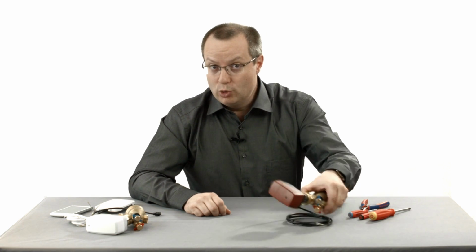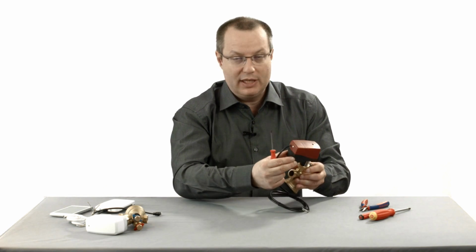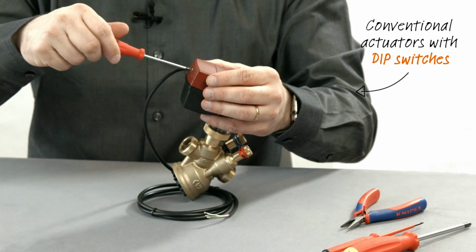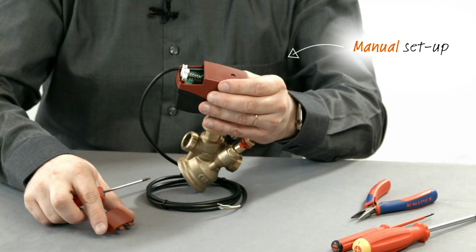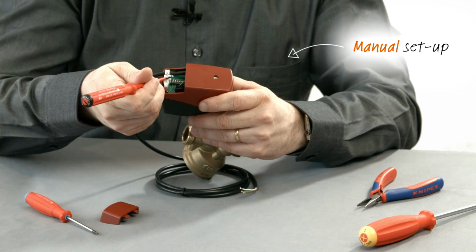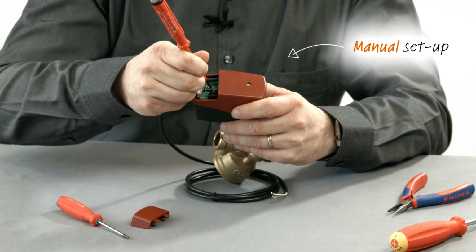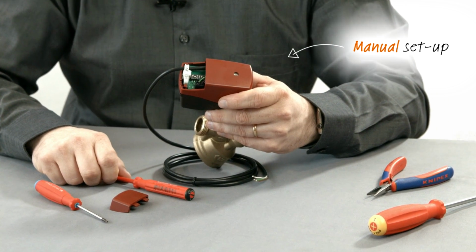To do this kind of configuration with traditional actuators, what you need to do is to get access to the actuator, bring along with you tools allowing to open the cover or compartment of the actuator, and access a rack of dip switches or jumpers, allowing one by one to make certain configuration choices in the actuator.